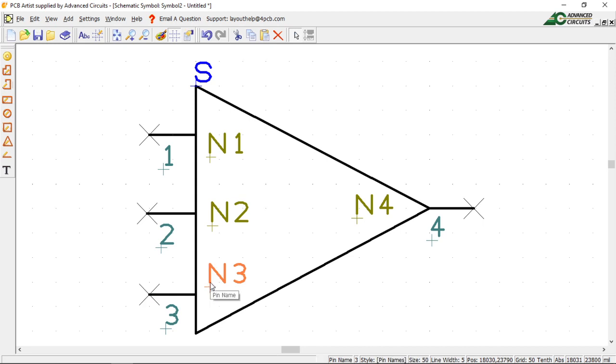It goes on, says some more stuff, and it says the symbol origin character, which is right here. Okay, and what we're going to do is we're going to put this right here. So it says that the symbol is on pin 1 if this pin is the first item added to the symbol. The pin numbers are automatically numbered, so on and so on.